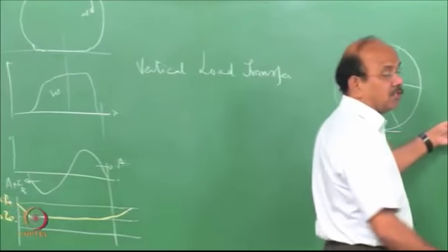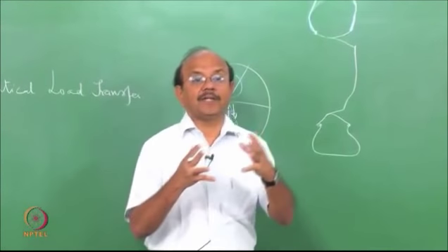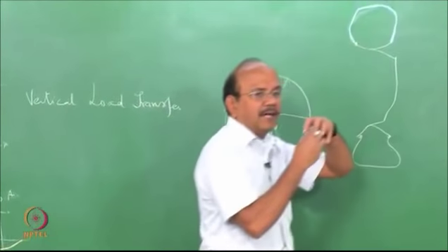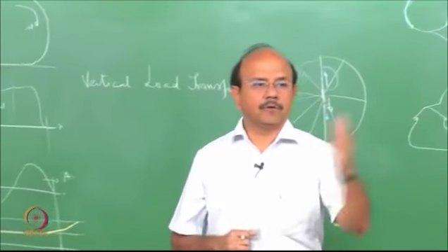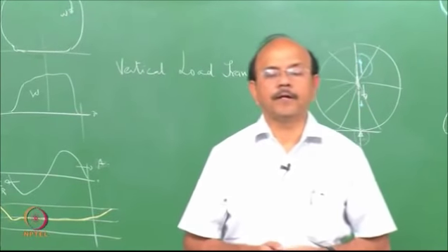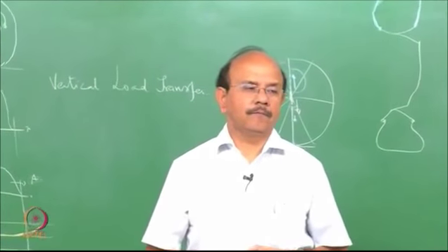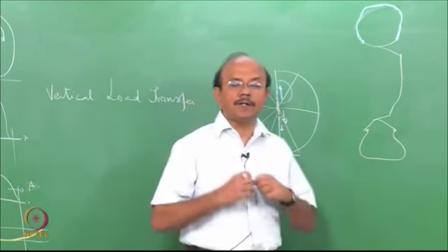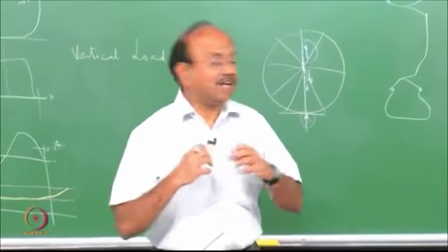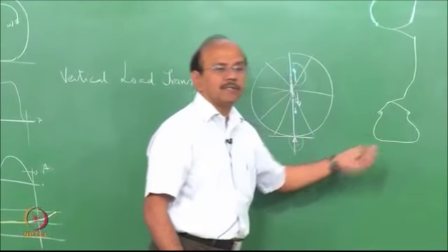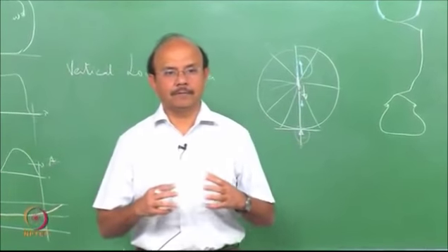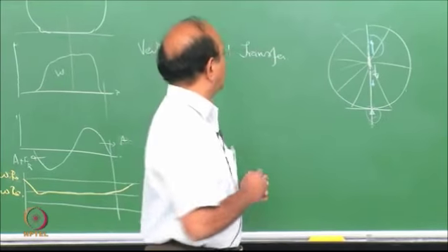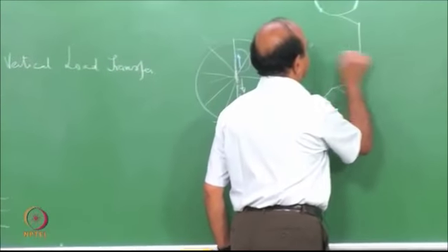Here the sidewall gets the tension from the pneumatic pressure, in other words the inflation pressure. You go to a shop and fill it up, 32 psi is the pressure you say you keep. So that pressure is what gives the sidewall the equivalent tension of a spoke. Is it clear? That gives the tension. Now let us see what happens. That is the axle.